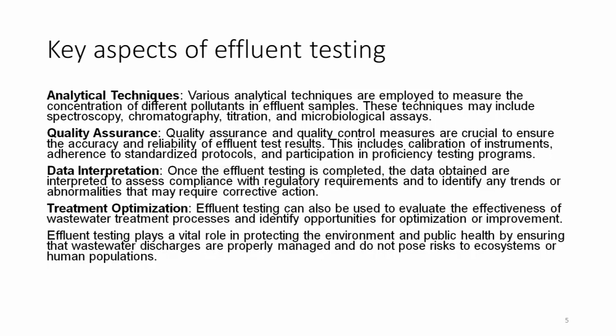Data interpretation: once the effluent testing is completed, the data obtained are interpreted to assess compliance with regulatory requirements and to identify any trends or abnormalities that may require corrective action. Treatment optimization: effluent testing can be used to evaluate the effectiveness of wastewater treatment processes and identify opportunities for optimization or improvement.